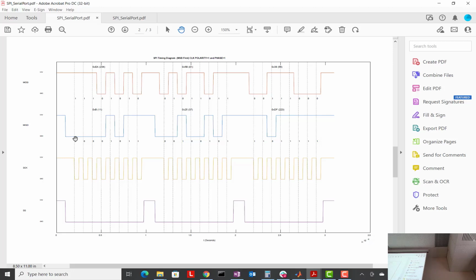Okay? And then we just do 1 bit at a time. Here we've got to remember though, different from the UART like we did in homework 1, the UART sent the least significant bit first, if you remember that. SPI sends the most significant bit first. Okay? So the number you get, like this says here, the least significant bit is the last one you get. And now the good news is the serial port knows this. The SPI serial port knows to put it in that order.